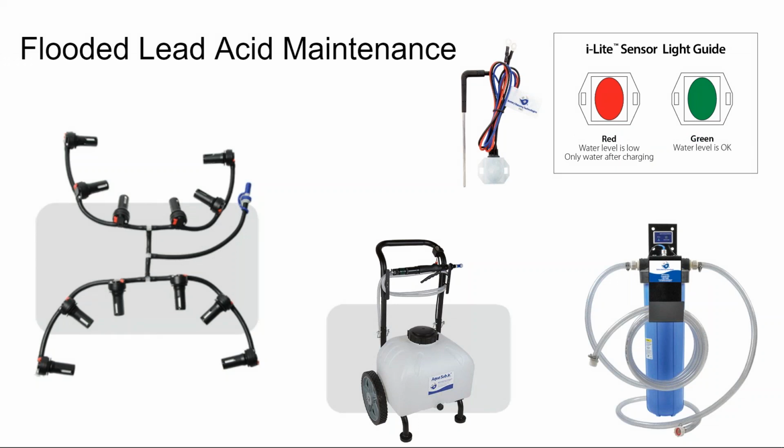What we're doing on my 2 recent projects is putting an air conditioner inside the battery box to provide heat in the winter and keep the battery box cool in the summer, programming it so that it only runs on stranded electricity, so it's not really increasing any electrical usage of the system. And then we're capturing the water from the air conditioner into a tank so the water's there on site, which is useful to me because hauling around a bunch of distilled water is kind of tedious. So I'd rather it just be there right next to the battery.